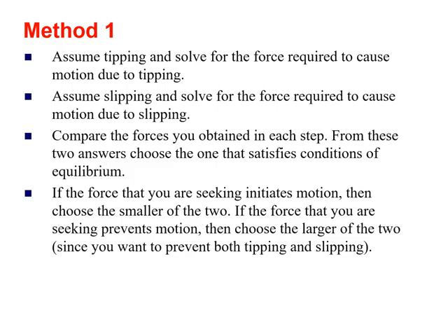Now the method of solving the numerical problem related to this tipping or slipping. Method one is to assume that the body is tipping. After assuming that the body is in tipping, solve for the force required to cause the motion due to the tipping. Second is to assume that the body is slipping and then again solve for the force required to cause the motion due to slipping by using the steps that I discussed in the previous slide.